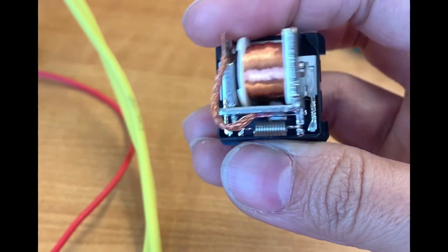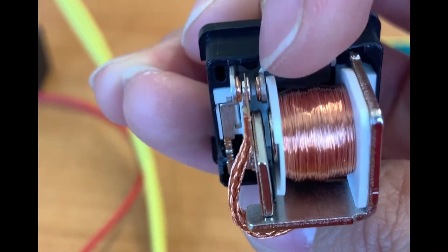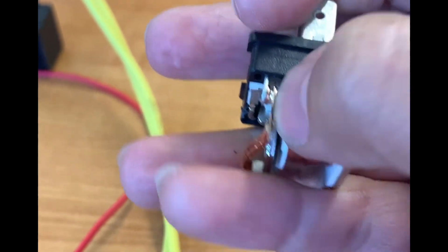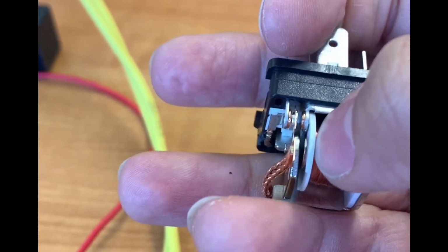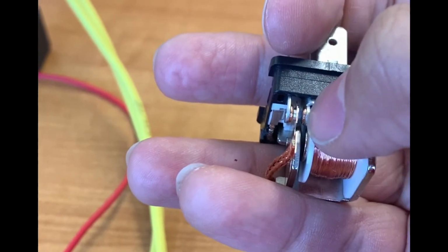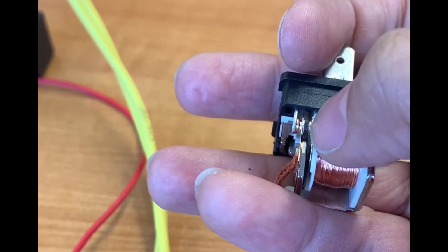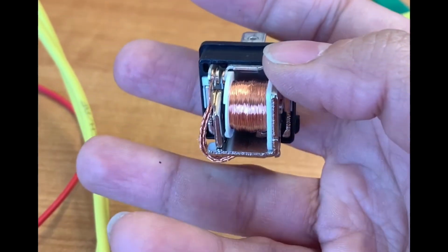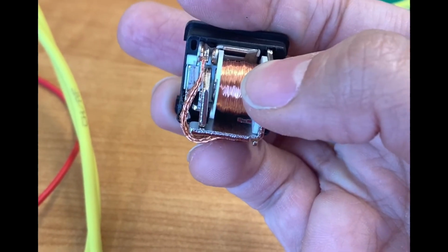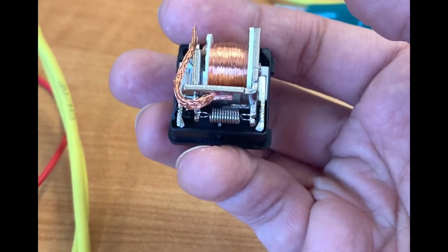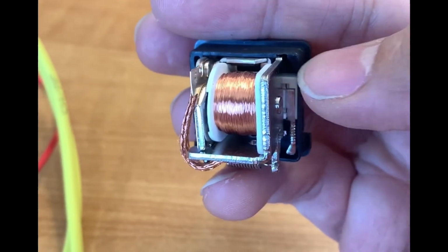Do you see the coil here? That is where the circuit gets connected and disconnected from here. And obviously this is our electromagnet, so it becomes magnetized and attracts this bit, and that attaches, and it closes the circuit. And when it's demagnetized, it means that when it goes lower than the voltage that's required for magnetizing this, then that will be open, so the circuit will be open. So it's working like a magnet switch. That's why relays are also called magnetic switches.